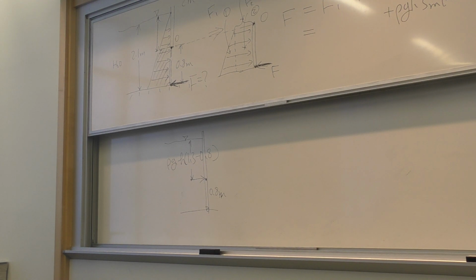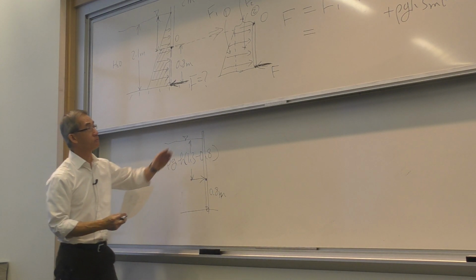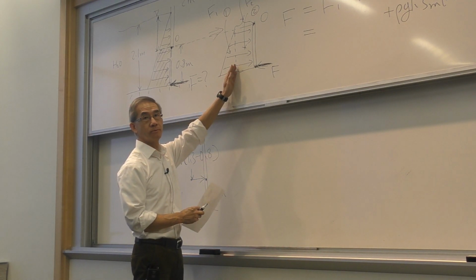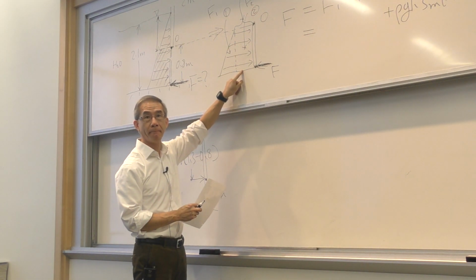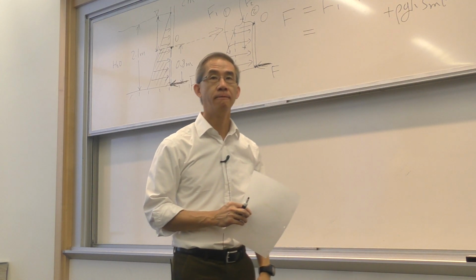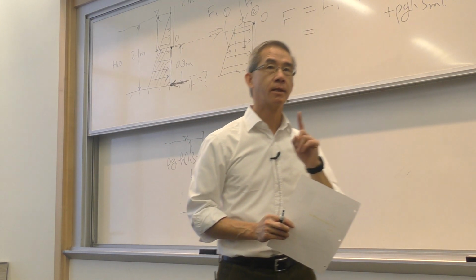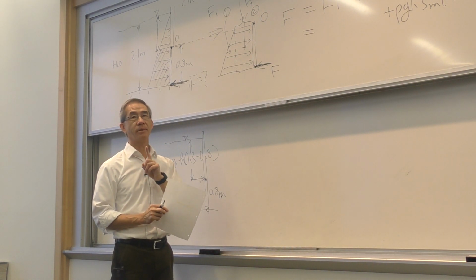Right? And that pressure, once I determine what it is, for this rectangle, that pressure is the same. Yes? How come it would be the same if you took rho g h to the bottom point? Wouldn't it be more than 1.3? It would be rho g times 3. It's the same because I cheated.